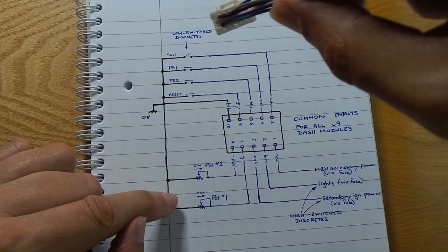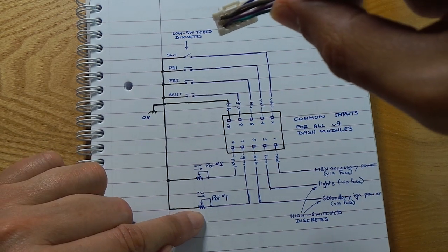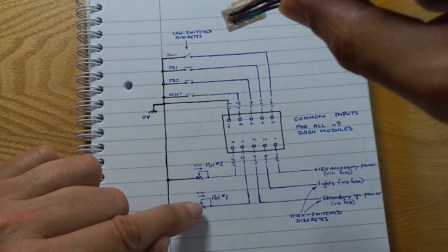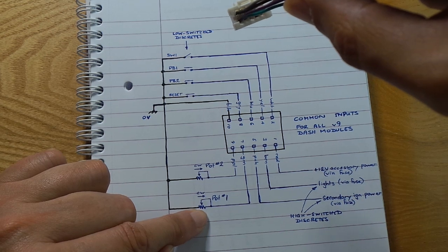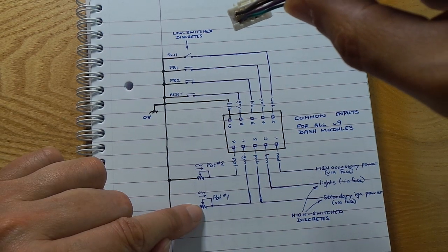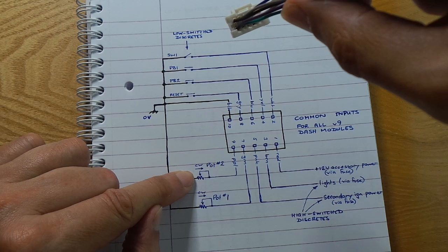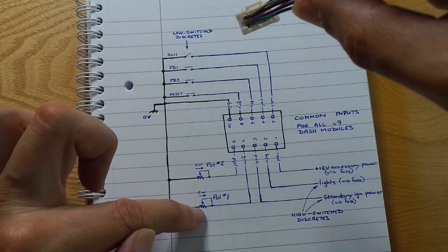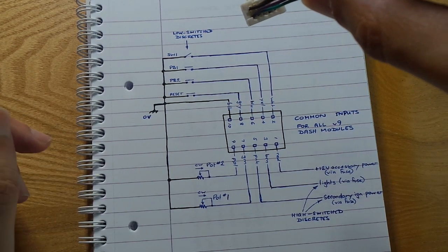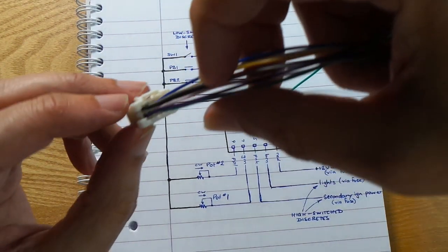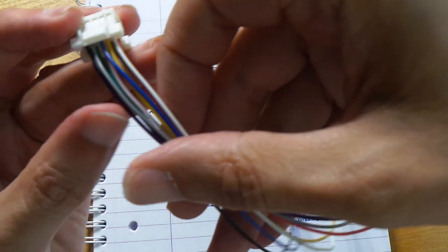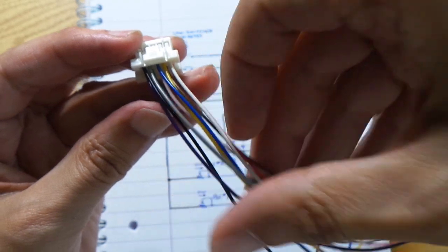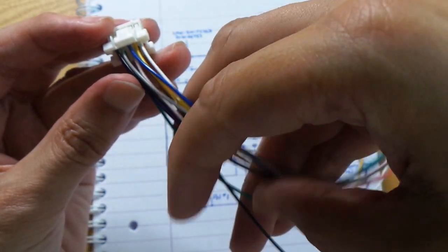There is an option, another user option, which allows us to just use the single potentiometer to drive both, but normally in the default configuration we'll have pot number 1 varying the brightness of the voice display, and pot number 2 varying the brightness of the side indicators and the NAP indicators. Again, as we've mentioned, if you don't connect those at all, that's no problem, it just gives you maximum brightness. And pin number 10, which is the leftmost pin on the upper row, is a black wire, and that is just a ground connection to the unit.